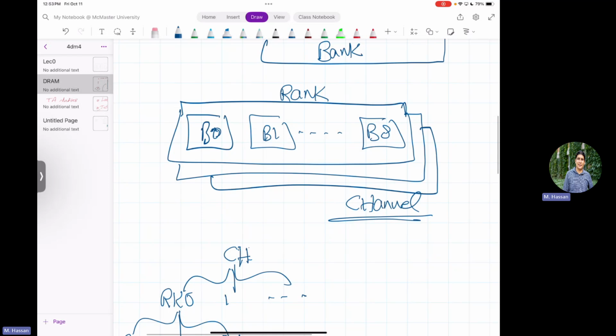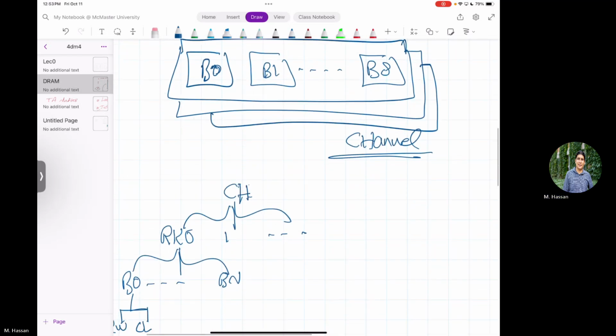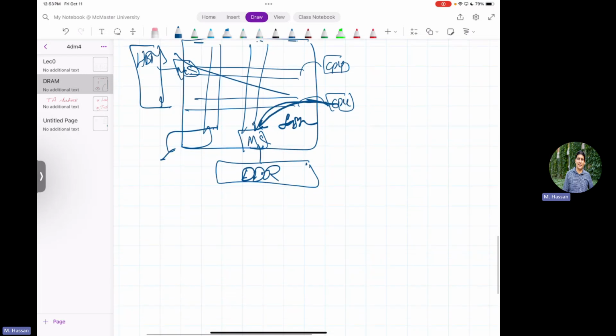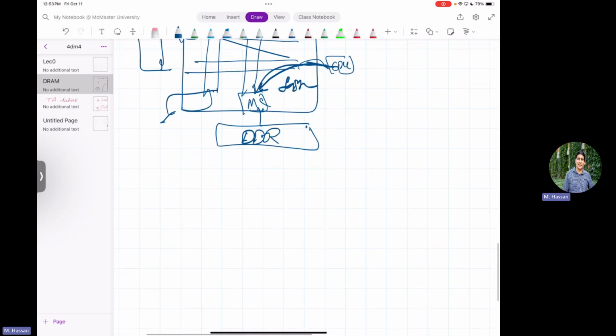Okay. So in that case, I want to serve those last level cache misses by sending them to the particular address, to the DRAM cell that has the data of this request, right? So I have a last level cache miss. It's a cache line miss with 64 bytes usually. I want to bring these 64 bytes from the off-chip memory to the last level cache, and then from the last level cache to the next level, etc., until it reaches the CPU, right? How do I do this? DRAM simply has no concept of a cache line.